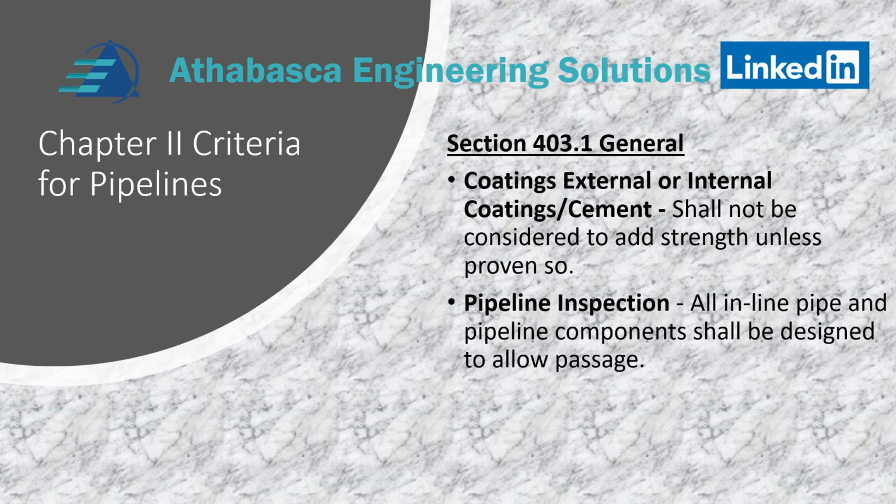Now onward to the last point, pipeline inspection. All the components, the inside diameter must be large enough to allow the line to be piggable. That's why you see a lot of specs for valves and stuff that they're all pipeline valves, and they're all part of the reason why there is all these different specs is for this piggability, like making sure your inside diameter and your clearances are acceptable.